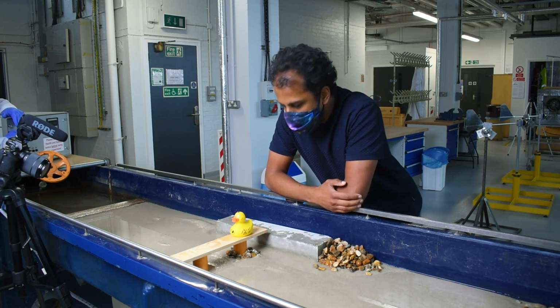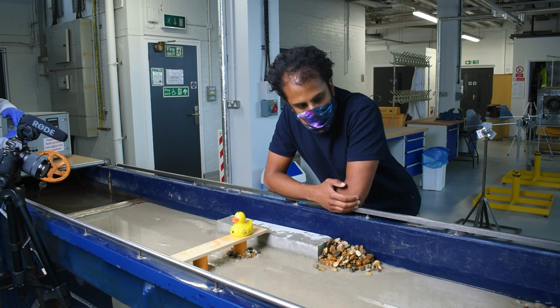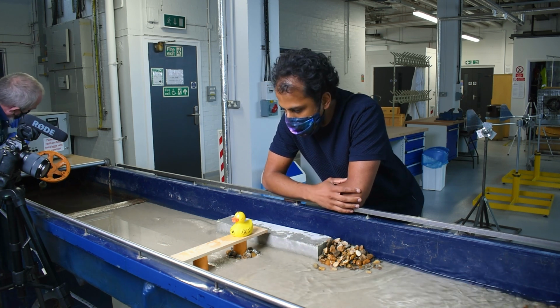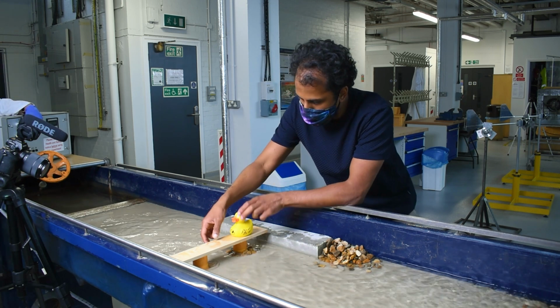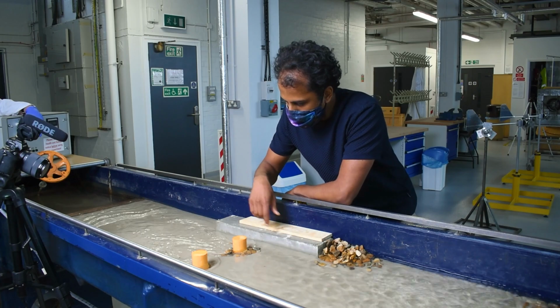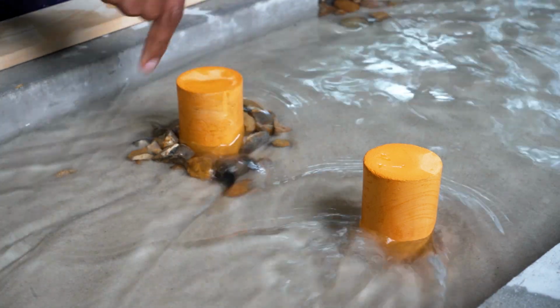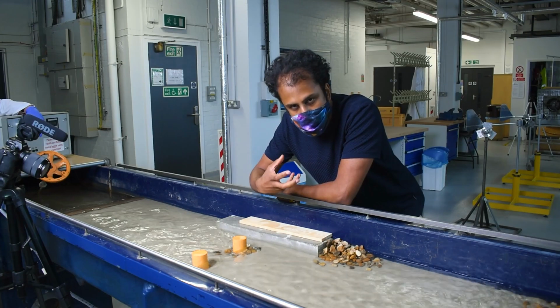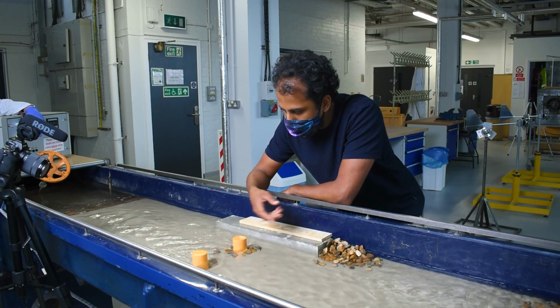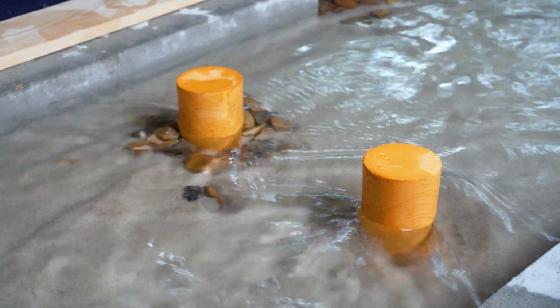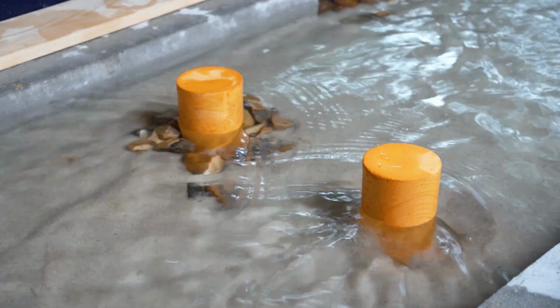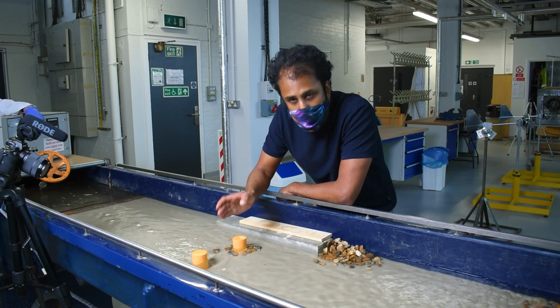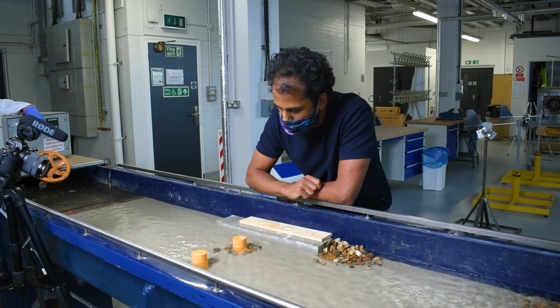Right, so this is part 2, where before COVID times, I'd get you to design scour protection for a bridge. Now this one has got some stones around it, some armour stones, to try and reduce the amount of scour that occurs, and this pier here is left unprotected. So that's probably going to fail. There's a very big scour hole already.